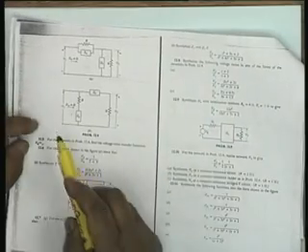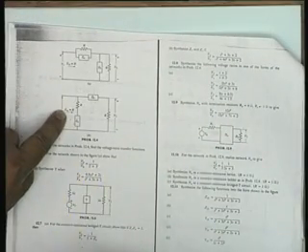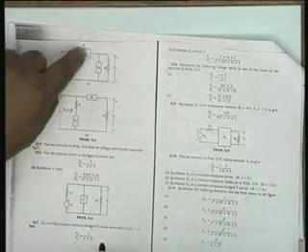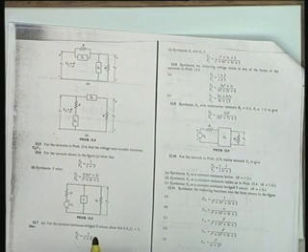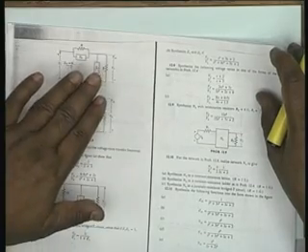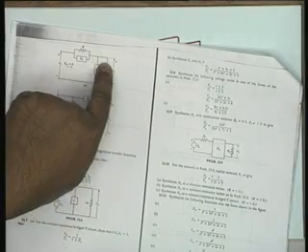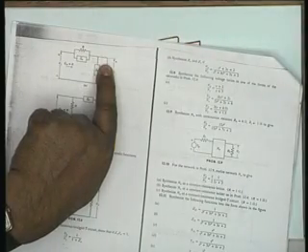What was your question? In 12.4, for proving the second circuit, we are going to terminate by R. No more termination; termination is already there. You have to show that the input impedance for the 12.4 second circuit is R. And for the A part, the termination is ZF parallel R or simply R. There is no other termination. This is the network, so it doesn't matter. Both of these are not constant resistance, so termination doesn't matter. But they are used in synthesis. You replace R by a second network of this type and terminate that in R. You see what I mean?